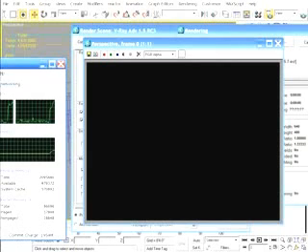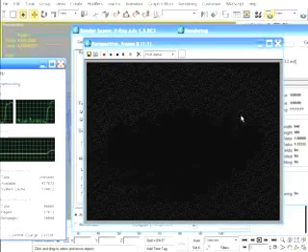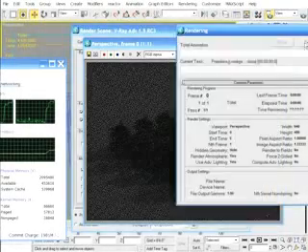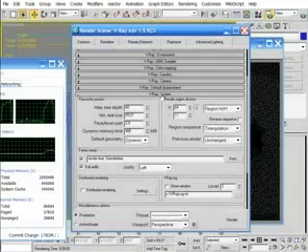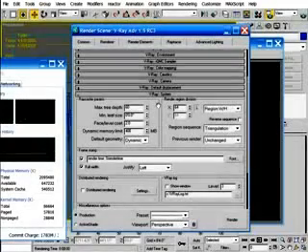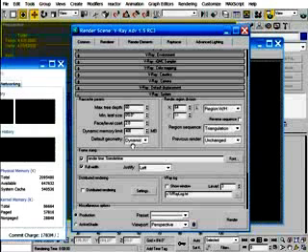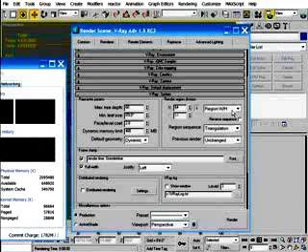Okay, well, certain object types are considered dynamic geometry regardless of which mode you render in. Examples of these are VRay proxies, VRay displacement mapped objects, and objects rendered with the VRay Fur feature. These types of objects are automatically treated as dynamic geometry, which is a good thing because if they were treated as static geometry, they would be drastically less useful, and VRay probably wouldn't even be able to render some scenes without running out of RAM.